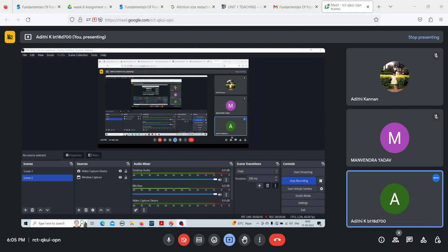As I told you before, there are three different empirical laws that we'll be discussing, and based on the law, your m value will change. c is a constant. According to Rittinger's law, m is equal to 2 here. That is, the energy required is proportional to the surface area of the particle. If you have x square here, where x is the dimension of the particle, it means that the energy required is proportional to the surface area of the particle.